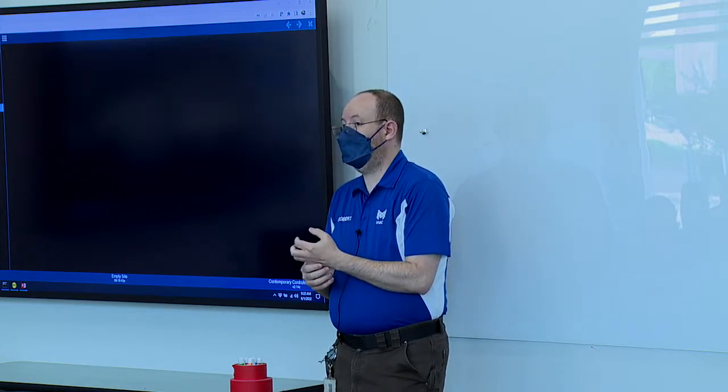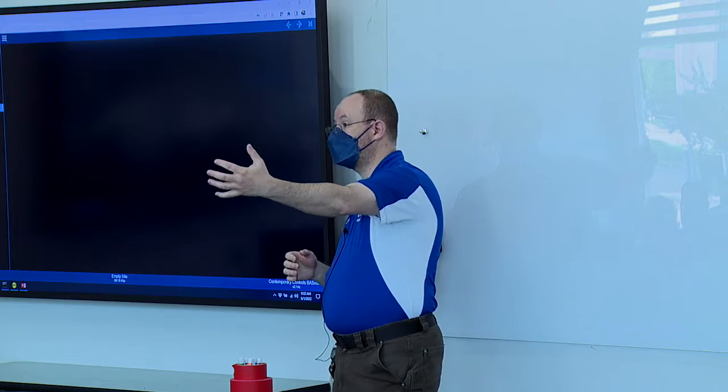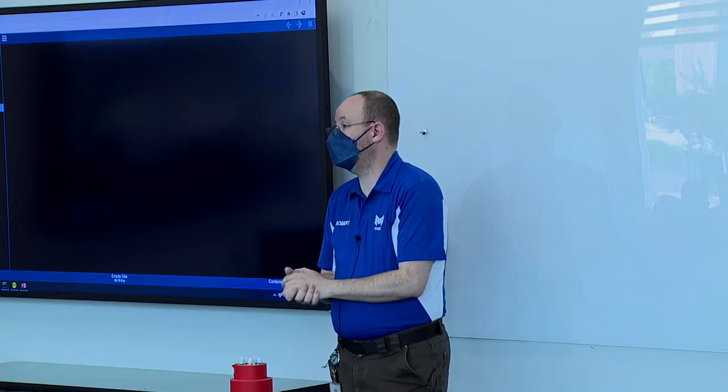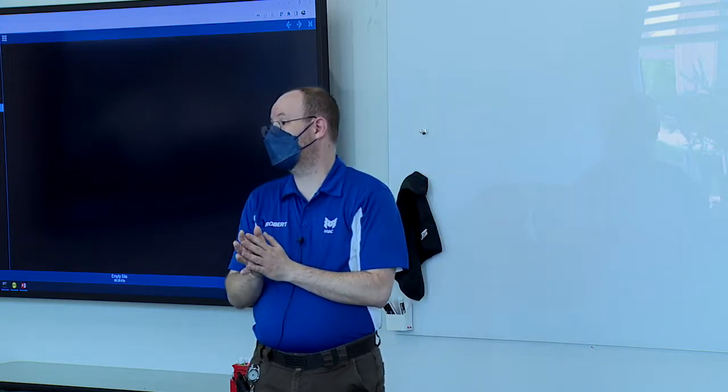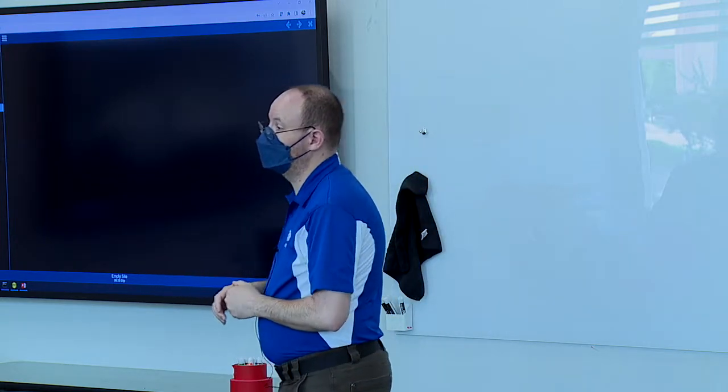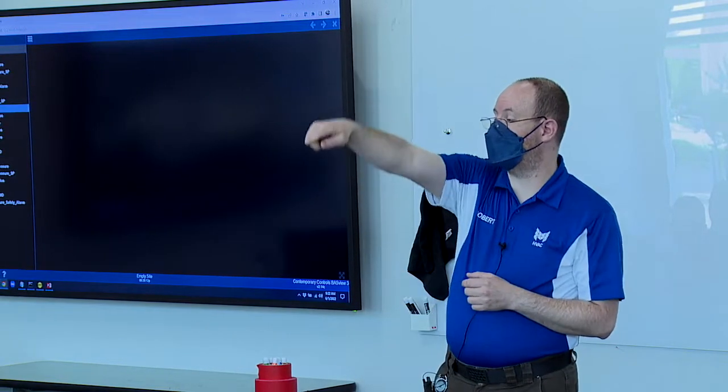Okay? And when you are programming a controller, you use a huge number of virtual points. All of your set points, or almost all of your set points, are virtual points, if it helps you think about it, because they are not typically tied to an input or an output. So everything that's not tied to those really is a virtual point. It's just a matter of where it's living. If it's living in the controller, it's the controller's virtual point. If it's living in your supervisor, it's your supervisor's virtual point. Okay?